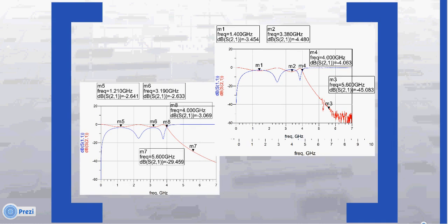We then met up with John Dang, where he took measurements of our filter so we could compare it with our simulated values. We were then able to upload our S2P file onto ADS to show our measured results. Here are the comparisons between our measured and simulated results.